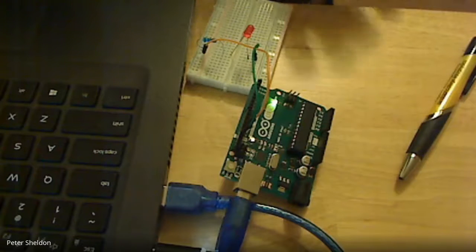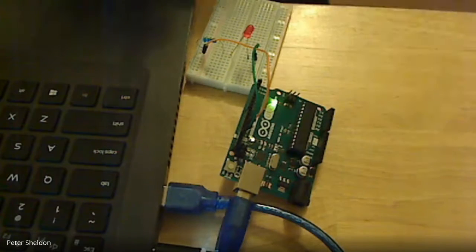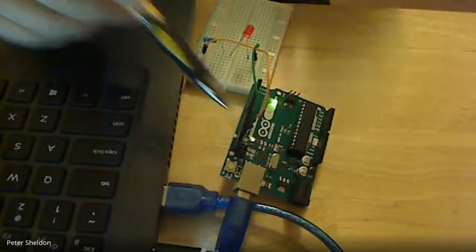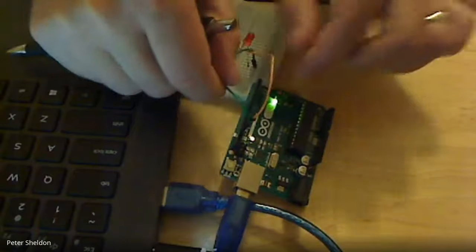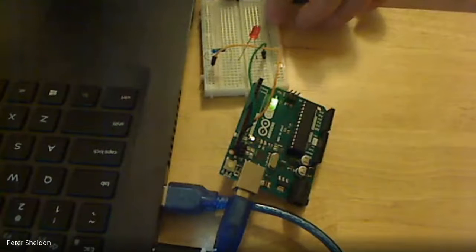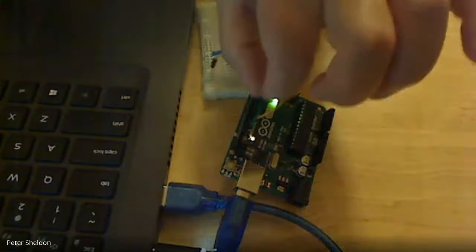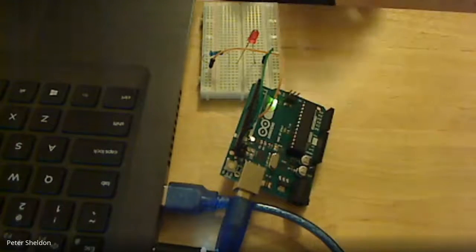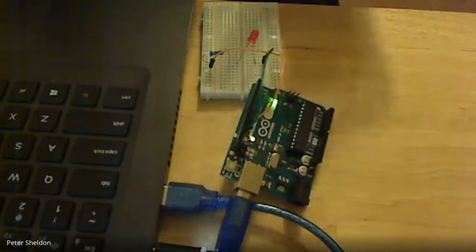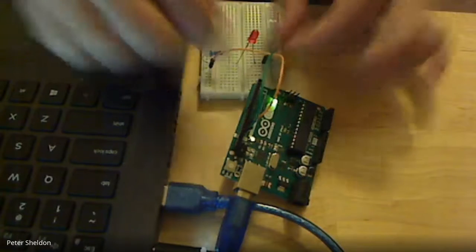I've attached an external circuit board. Hopefully I got it on pin 12 here. I just plugged it into the board, hopefully in pin 12 with a jumper wire. And there's also a ground pin. So remember, in this case, the board is going to be our power supply. And so pin 12 and a ground wire. Those are my two orange and green wires.